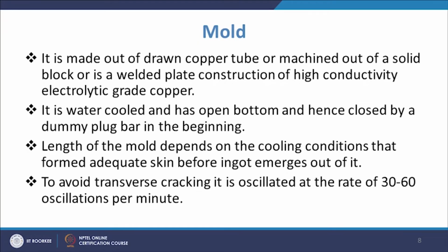But then, as we discussed, since the melting temperature of copper is smaller as compared to that of steel, we need to have another cooling mechanism constantly, so that it can take the heat away quickly and it should not melt. For that it is normally water cooled and has an open bottom, and hence closed by a dummy plug bar in the beginning.